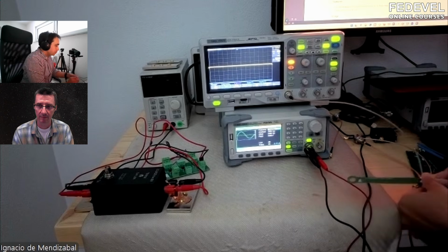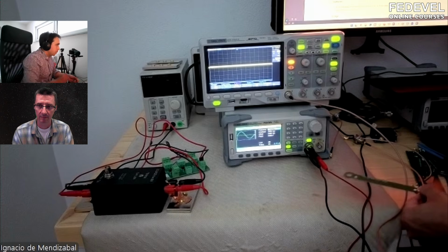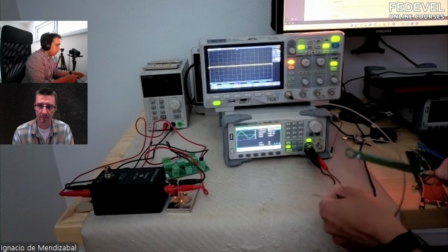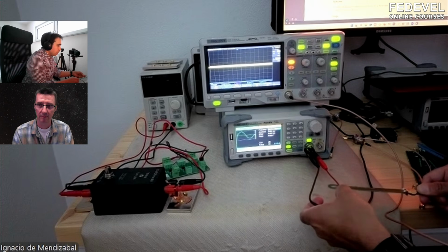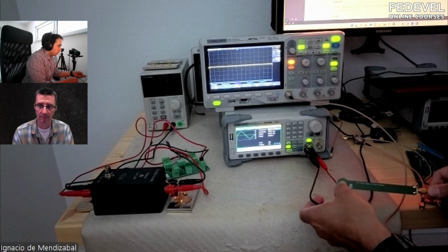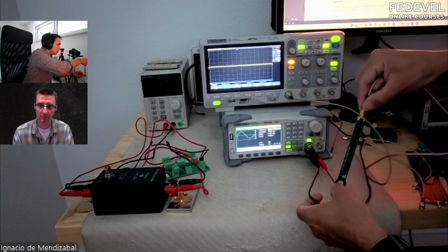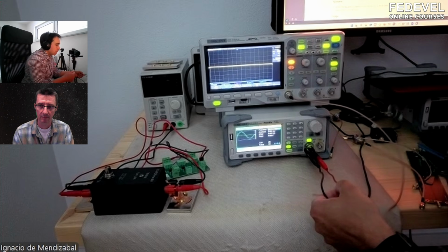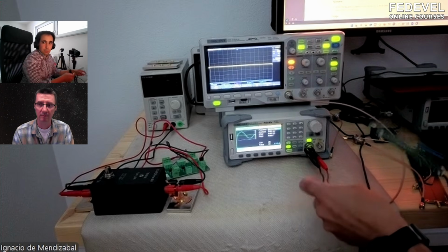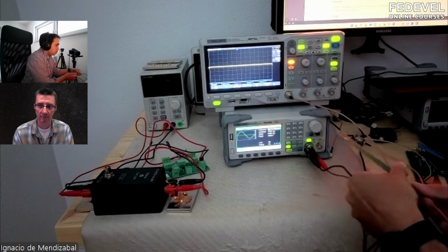Here we already see that we are measuring. For example, if we place the probe directly over the cable, we are measuring. But if we start rotating the probe, the signal is different. So you need to play with these three factors: first the type of probe, the size of the probe, and the orientation. So let me